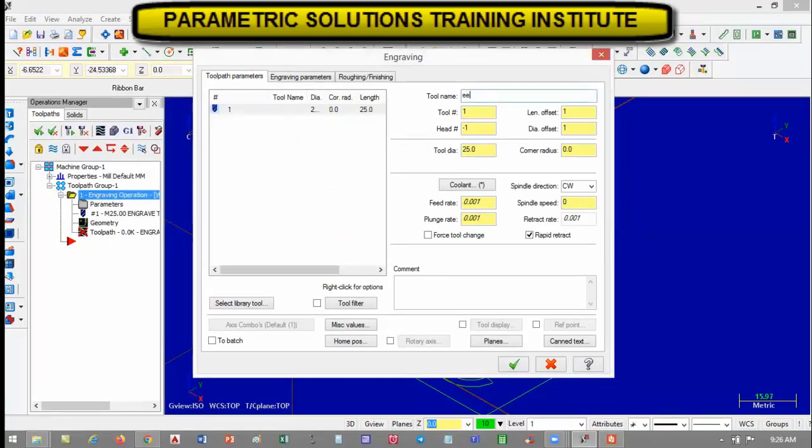I've selected the tool holder. Then tool name, you can enter anything. Then number 4 for the tool holder from the tool post or else a spindle. Then cutting feed 30 per minute. Then spindle speed is 1500 RPM, revolutions per minute. So this parameter is important to enter. The plunge rate is when the tool is entering, that time what is the feed?